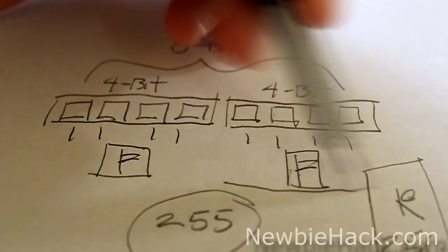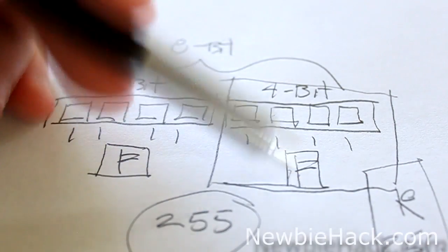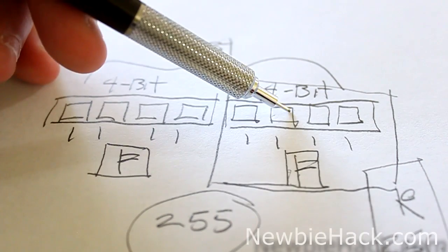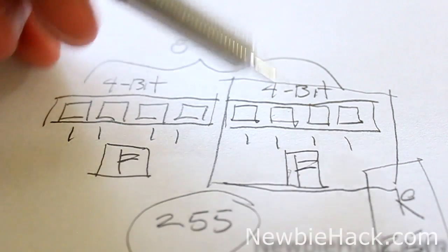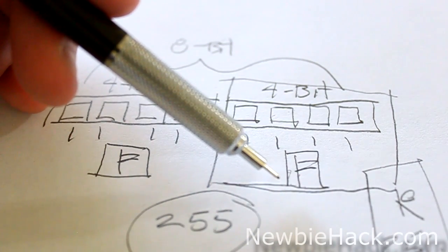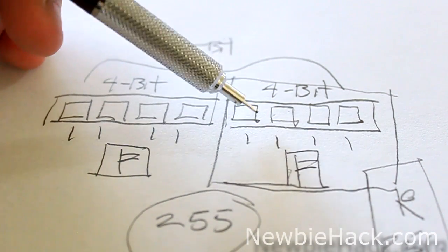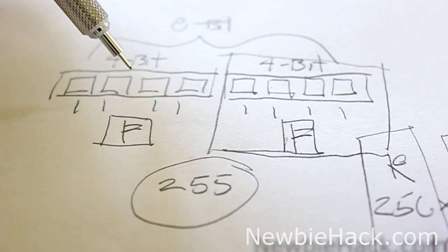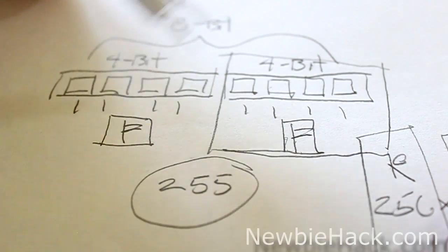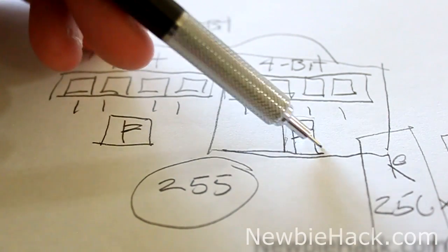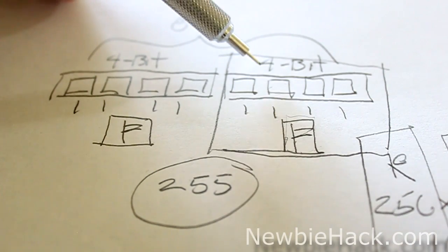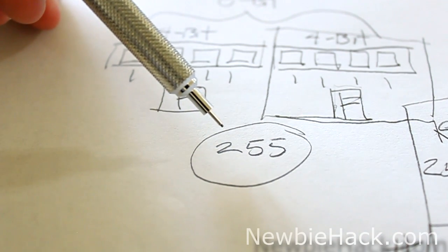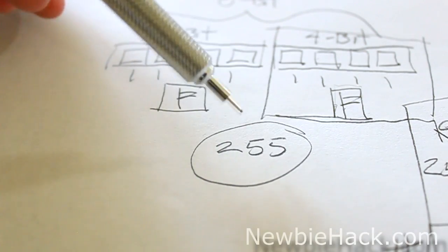And all you really need to know is this amount of information, a 4-bit number, and how to get a hexadecimal digit out of 4 bits. So let's go ahead and just do a 4-bit number. We'll do the 16 numbers, 0 through 15, in hexadecimal and binary. We'll just do a chart, a sequence from 0 to 15, which is 0 to F in hexadecimal, or 0 to 1111 in a 4-bit binary number. Once you have the understanding of the hexadecimal and the 4-bit binary number, you can put those together to make an 8-bit. You can put those together to make a 16-bit, a 32-bit, or a 64-bit, and then it becomes very easy to understand the hexadecimal number compared to a binary number. And you can also see how decimal really does kind of suck when working with microcontrollers and understanding the number system. So don't worry about getting into the decimal number system.